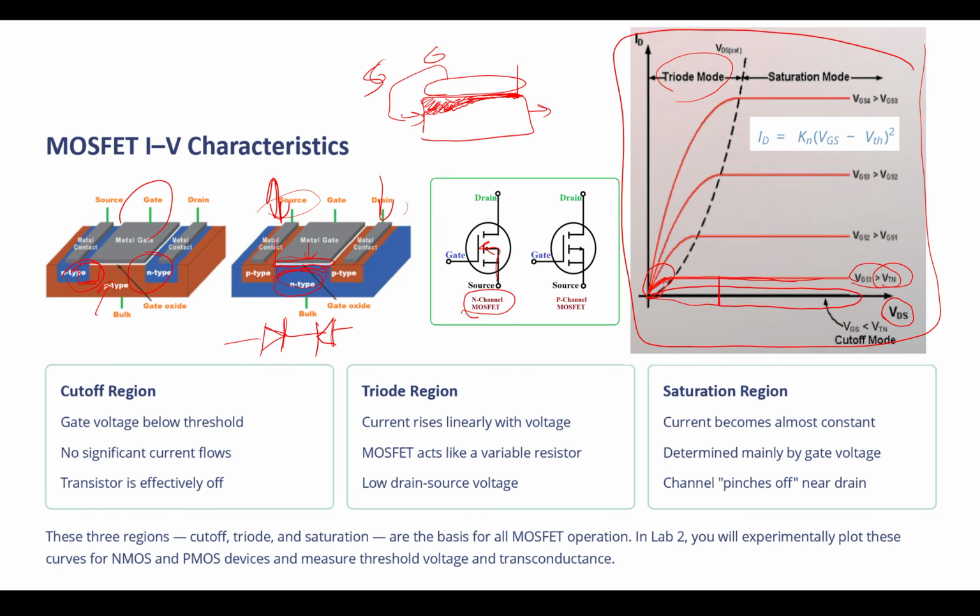In that mode, the drain current is still dependent on the voltage between drain and source because the channel is not saturated, so as much as you increase the voltage, you are going to increase the current. But when you hit the saturation part, it doesn't matter what the voltage between drain and source is, current would not pass over that saturation bar. Then, as the name says, you enter the saturation region.